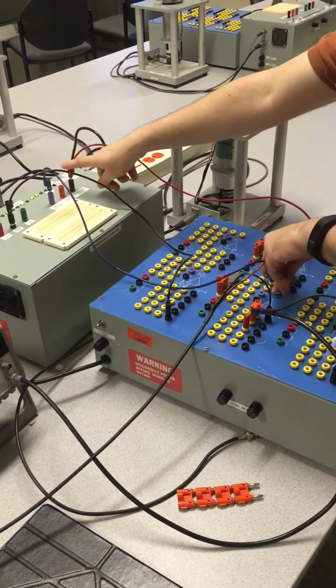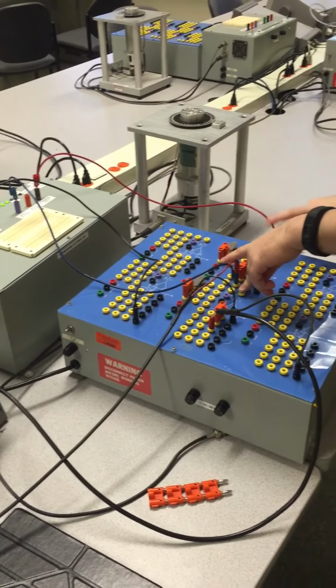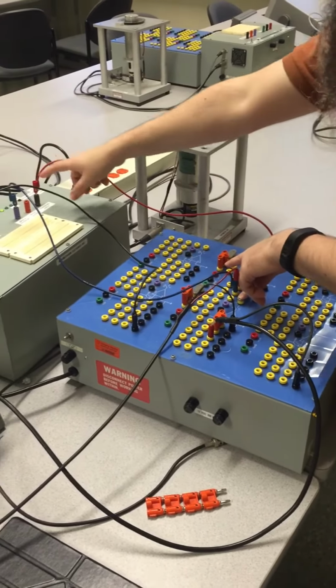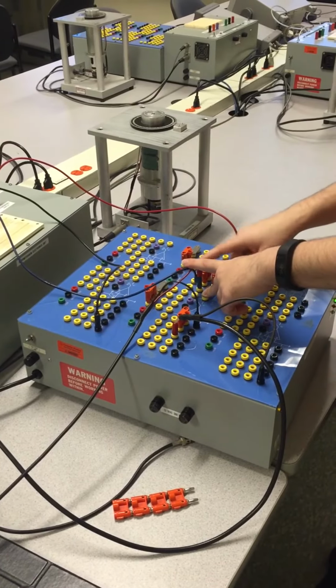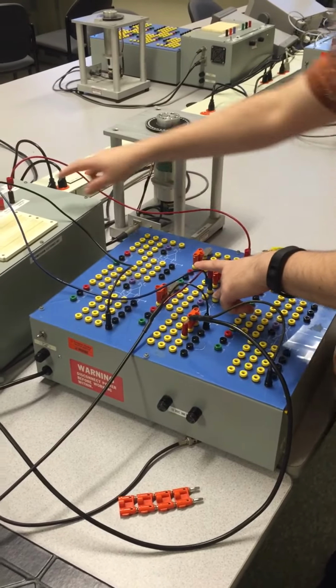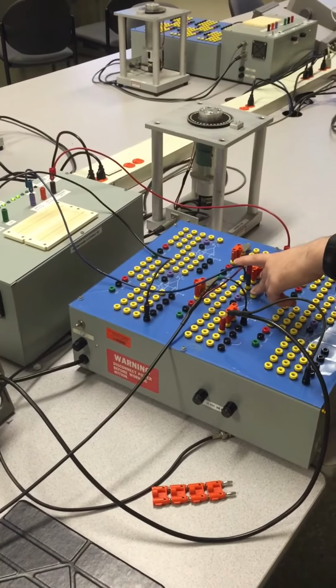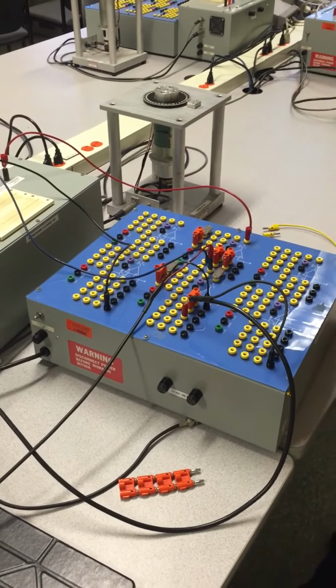So I ask the motor to do nothing. If the angle is higher, the command input will have a negative value. So this will make the motor move in the opposite direction. If the angle is lower than the target, it will have a positive value here that will ask the motor to move in the positive direction. So it always asks the motor to go in the right direction we want.